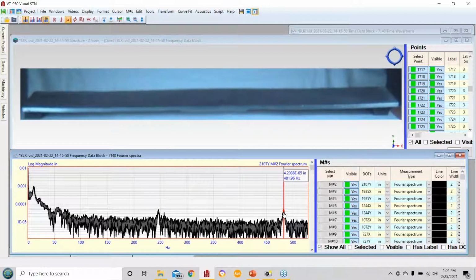It's not straightforward, but like anything, the video analysis gets you into tough spots where you can't actually put transducers on equipment. And one of the things that I worked on this week, I'll show you in a minute, turned out to be kind of an inaccessible thing. It was built for ODS videos because I could never possibly take measurements on it all. But in the video, 5 minutes of video and I'm ready to go. I have a nice modal analysis of the structure. So let me get into that.